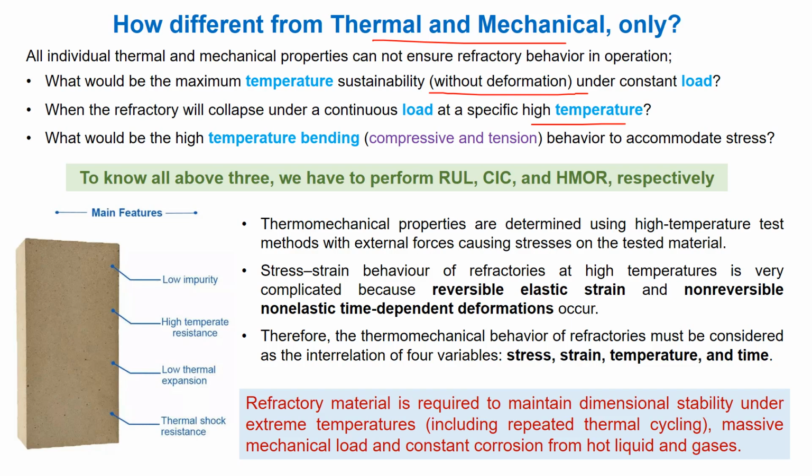What will be the bending, compressive and tension combined behavior at high temperature to accommodate stress? To know all the above three, we have to perform refractoriness under load, creep in compression and hot modulus of rupture respectively.